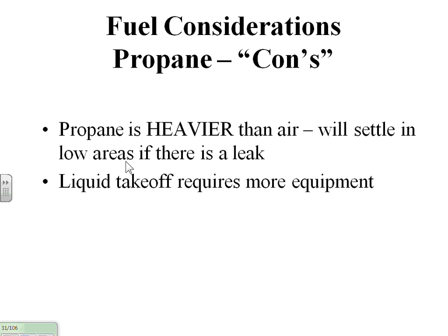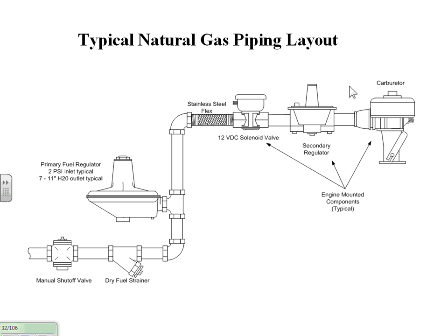Liquid takeoff requires more equipment. That's another negative, because we've got the vaporizer that I told you about. So, that's the cons for propane. Typical systems look like this. These are engine-mounted components here.